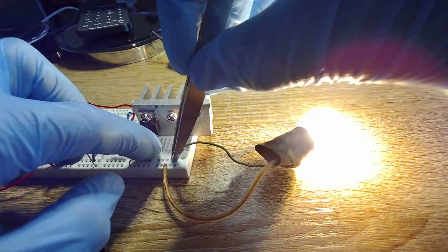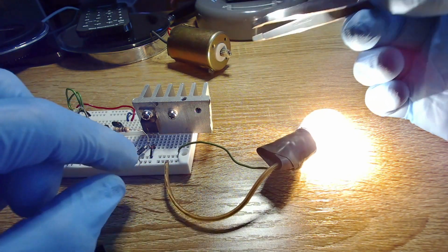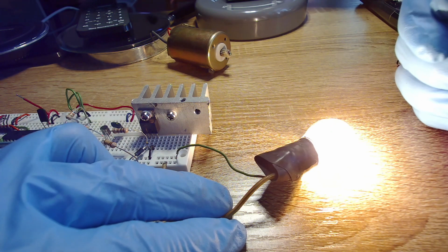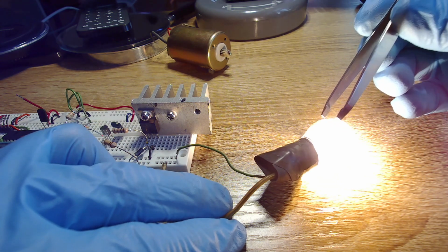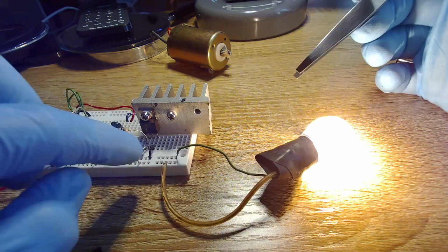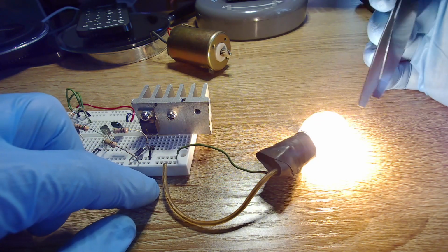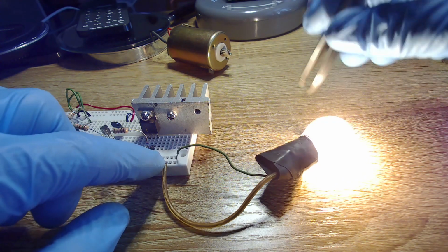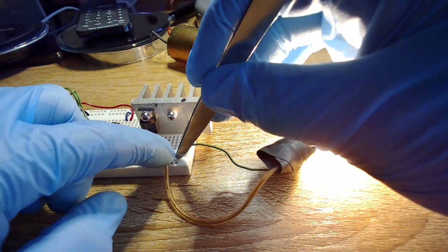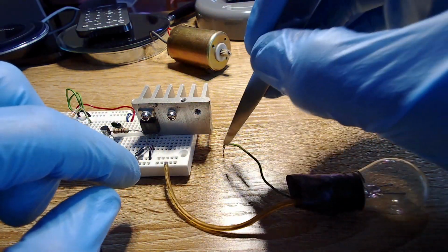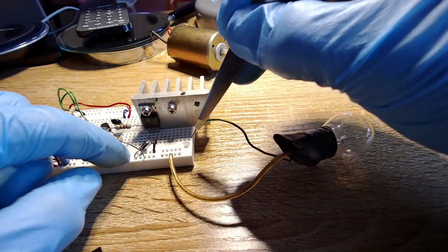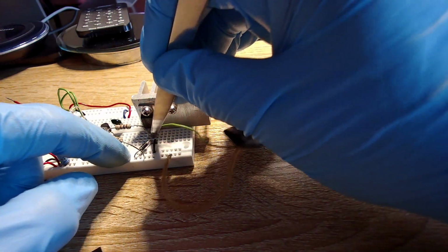And if that doesn't make sense, what happens is all of the voltage is now occurring across the light bulb, inside of this light bulb. So you will actually now see ground here and 12 volts here, and all the power is dissipated, of course, in the light bulb. Okay, that was a little bit of a digression, but the continuity thing is important. So to ground it is just as legit as to connect the power.